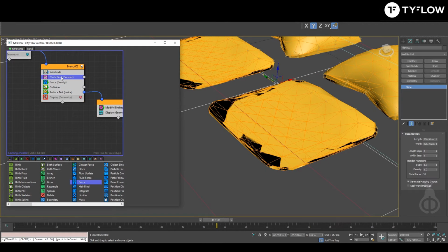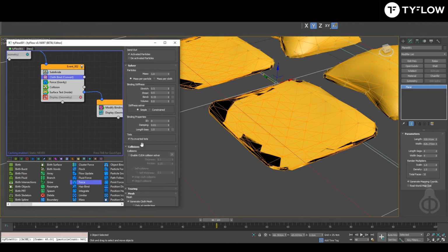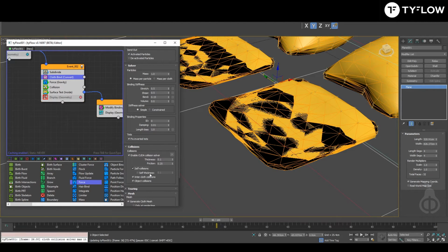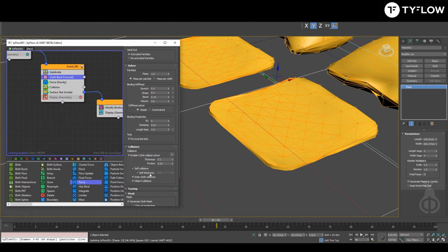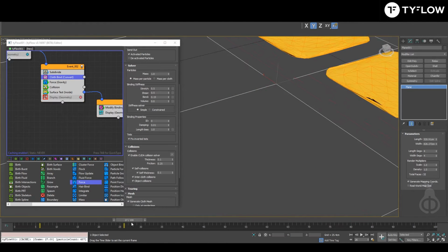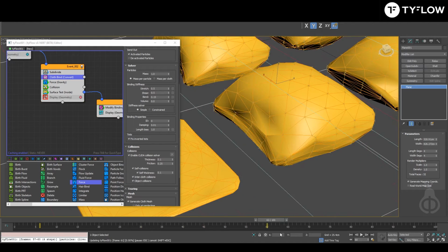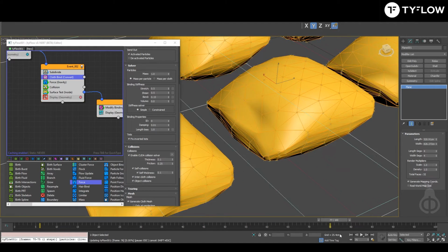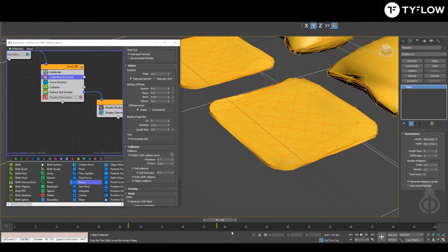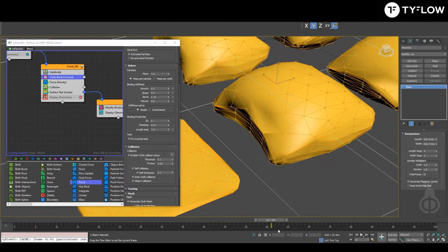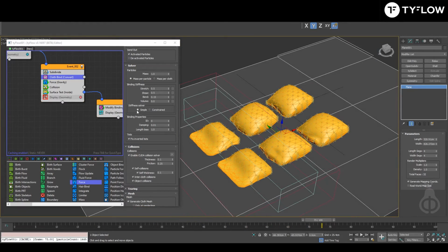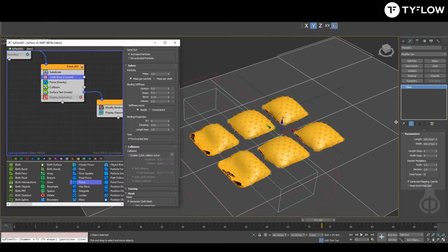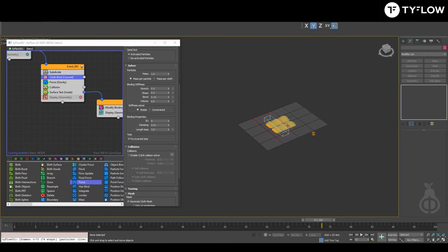You have two options. One is to enable CUDA collision and put self collision, self thickness. This is gonna fix at the cost of being more heavy to calculate, but will be more accurate. Or what I did in my case to avoid this visual issue, because the result without CUDA was fine for me, was to put in tyFlow